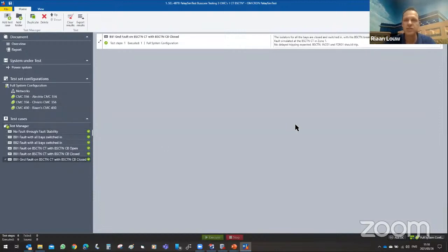Another thing to also mention is here, if you look on the right-hand side I've got a comment section. So for each of these tests that I've simulated today, I've added a brief description of what I'm expecting to happen even before I'm testing. So if you want to reuse this test template and another engineer or test technician is using this, just by referencing the comments in here, you can have a broader understanding of what is expected to happen and simulate the test and run the tests.